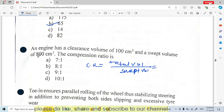Total volume is swept volume plus clearance volume. This is swept volume Vs plus Vc divided by Vs. So given Vs, swept volume, is 800 plus Vc given 100.